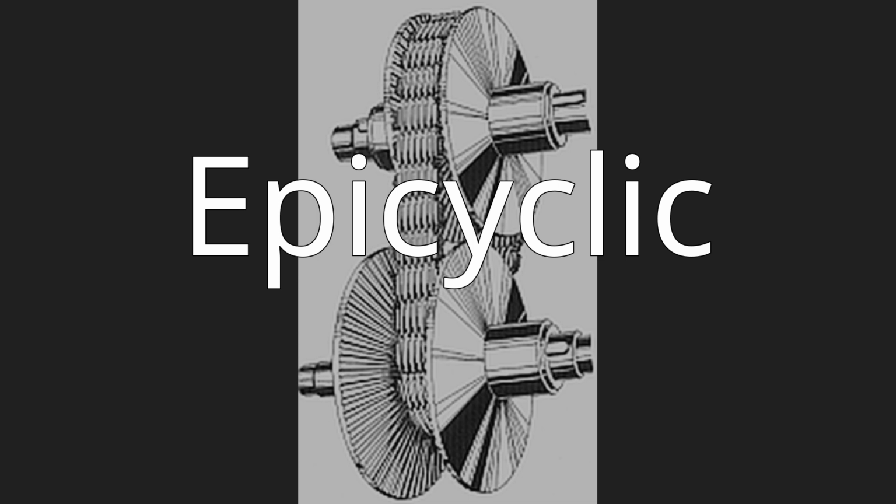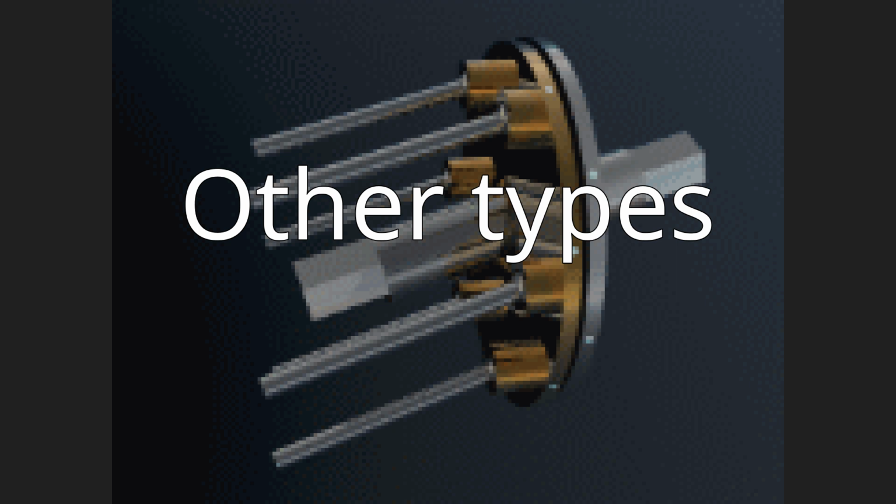Epicyclic. In an epicyclic CVT, also called a planetary CVT, the gear ratio is shifted by tilting the axis of spherical rollers to provide different contact radii, which in turn drive input and output discs. Other types, friction disc transmissions, were used in several tractors and small locomotives built in the early 20th century.